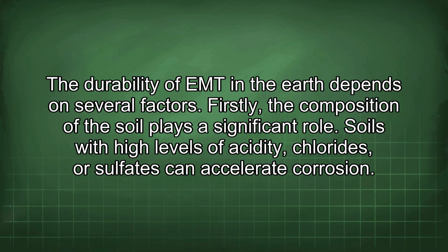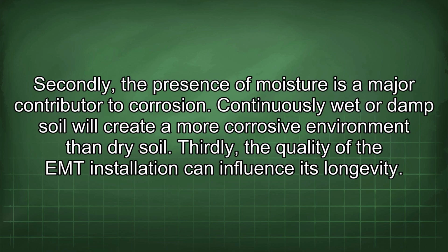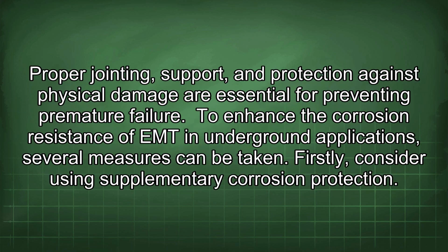The durability of EMT in the earth depends on several factors. Firstly, the composition of the soil plays a significant role. Soils with high levels of acidity, chlorides, or sulfates can accelerate corrosion. Secondly, the presence of moisture is a major contributor to corrosion. Continuously wet or damp soil will create a more corrosive environment than dry soil. Thirdly, the quality of the EMT installation can influence its longevity. Proper jointing, support, and protection against physical damage are essential for preventing premature failure.